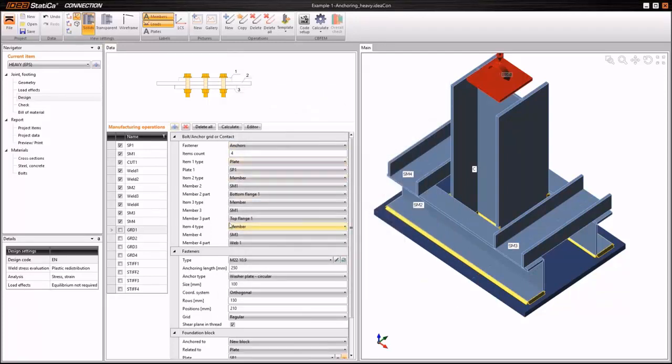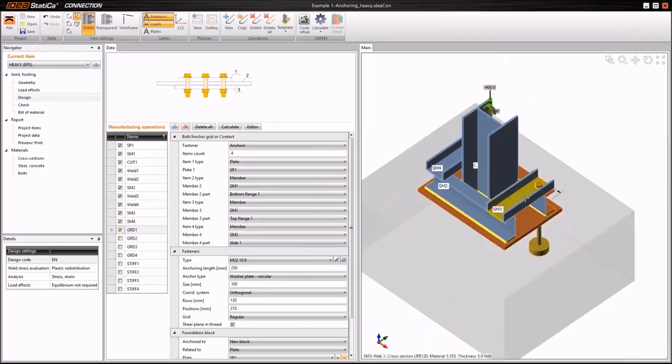You can see the dialog. I can switch it on, and you can notice that we add anchor and concrete block. And we can go through the dialog a little bit. In the first part, you can see that we add anchors. If we unroll this possibility, we can add bolts or contacts, but at this time we use anchors.